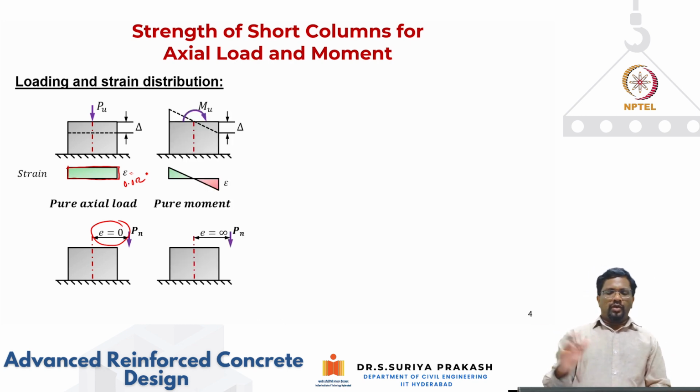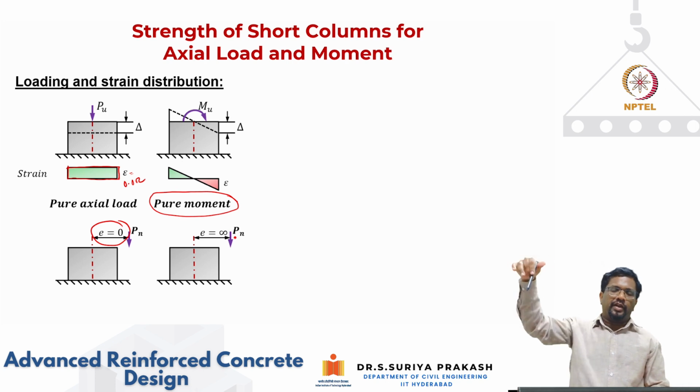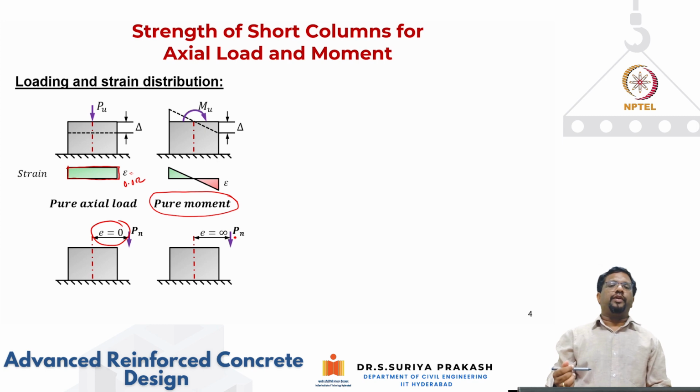Now you can have the other extreme, when the column is subjected to pure bending moment. Here the eccentricity of the applied axial compression will be at a very large distance. Theoretically, it will be at an eccentricity of infinity. Then only does the column feel just the effect of bending, which is basically pure moment.